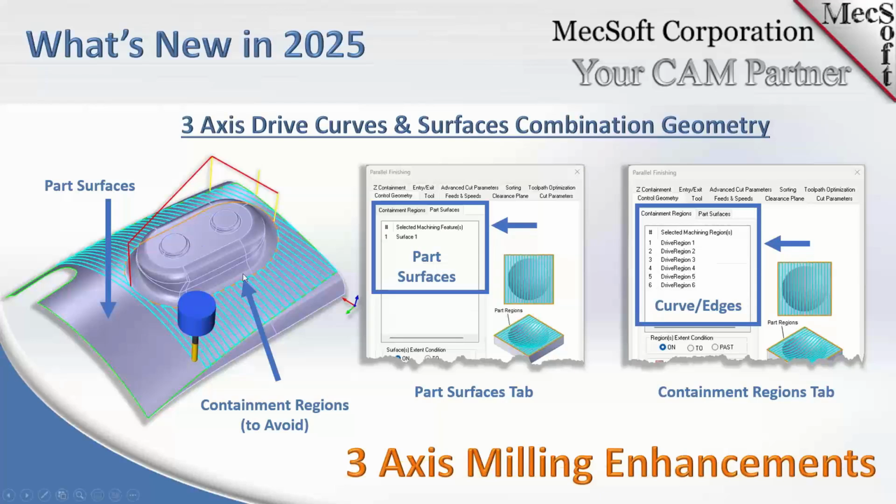And if you look at the picture over here, we're selecting one part surface in the part surfaces tab, and this is parallel finishing, 3-axis. And then over on the containment regions tab, we've added these curves, as you can see in orange here, that go around the base of this feature. So the result is parallel finishing will only take place between those two areas, to the perimeter of the surface, and then stops at the inner curve region.